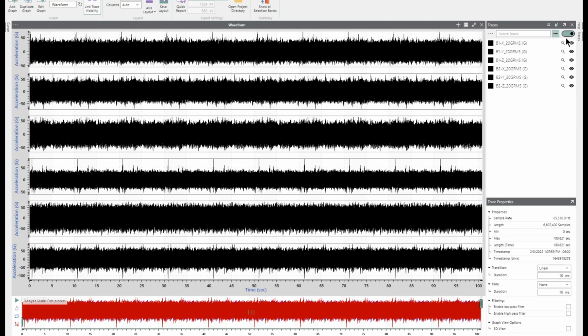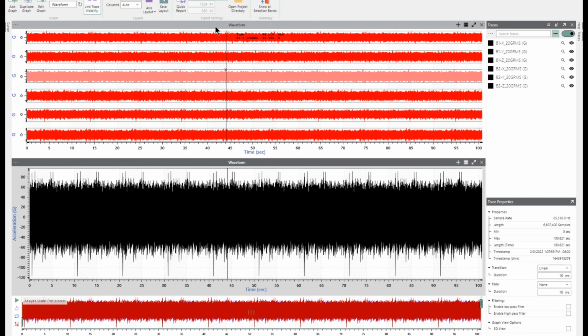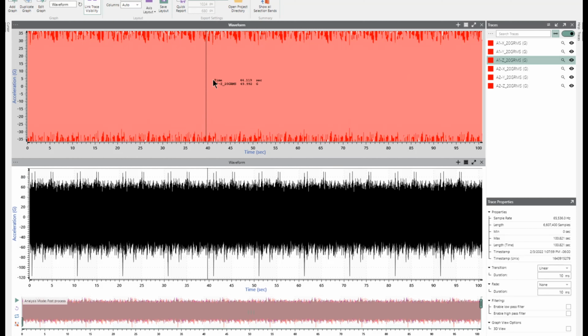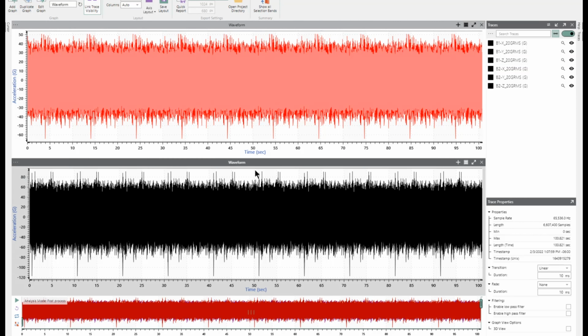And if we overlay all of these on top of each other again and start to look at machine A versus machine B, you can see that the relative peak accelerations for A are in that 40 to 50 G peak range. You have a few extremes out beyond. And then, this is in the 60 to 80. So obviously, black is higher in amplitude than red.